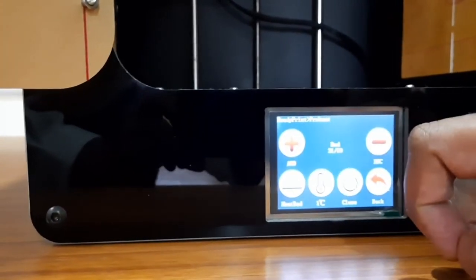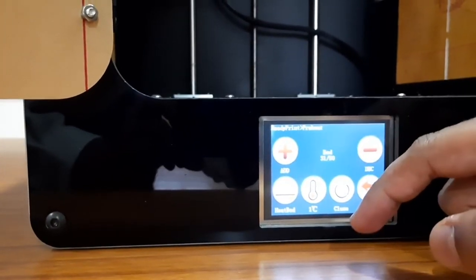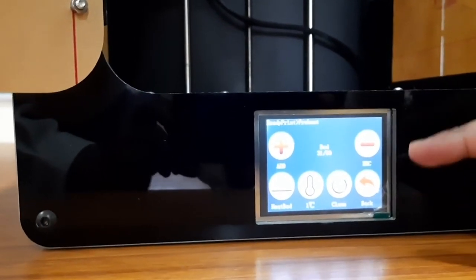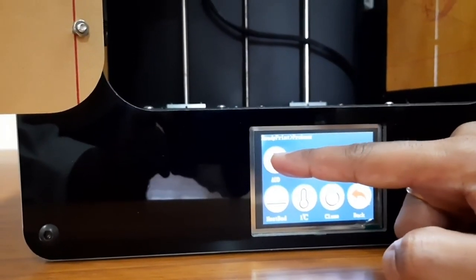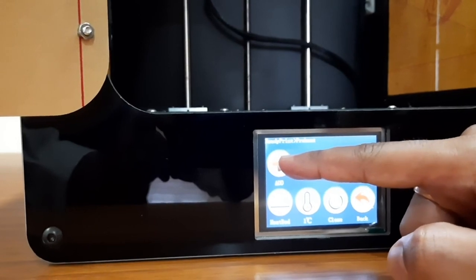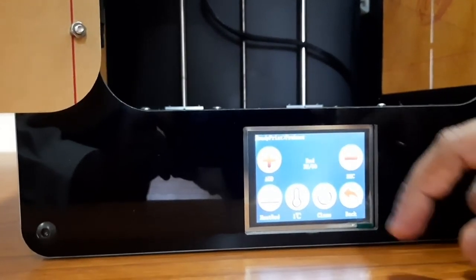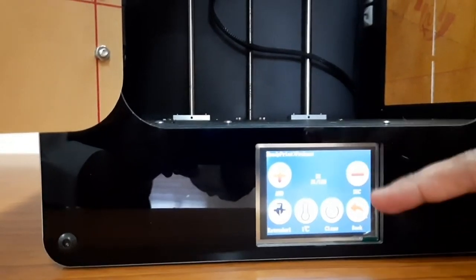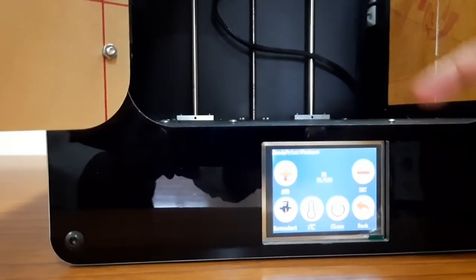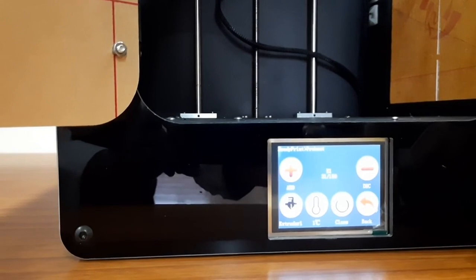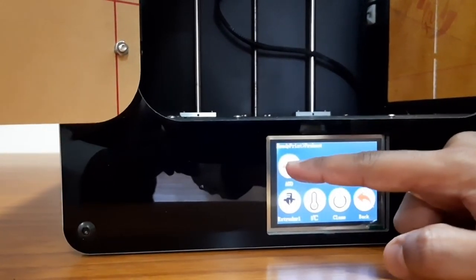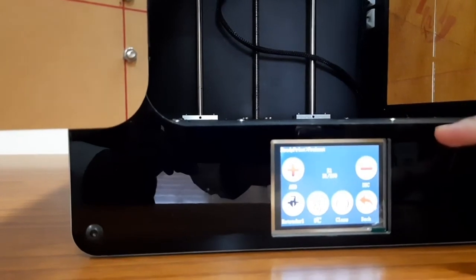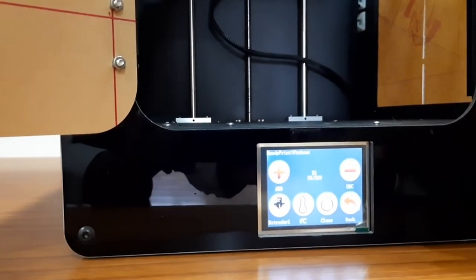We have to click on the preheat. In this preheat, now it is showing the bed temperature. The bed temperature is 50. Let us make it 60. Now when we click on the heat bed, it will ask for the printing temperature. It is showing 180. We have to make it 200. So these are the minimum settings that we do in 3D printing.